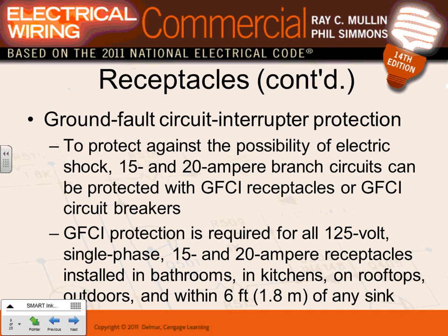Okay. Moving on into GFCI. GFCI this time is for non-residential. Now remember all the residential stuff that we did, Adam? It's in the back of your mind. 2 feet from the sink, and all the countertop receptacles in the dwelling have to be GFCI. Now we're moving to non-dwelling.